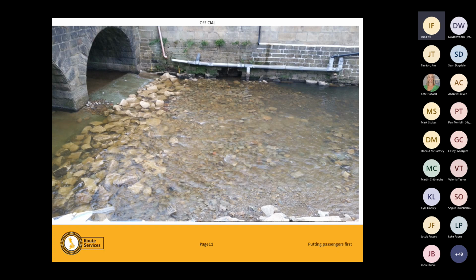So you've got fast moving water coming along through the structure, you've got slow moving water in the channel, and they crash into each other. And again, you get a lot of turbulence, a lot of energy. And what happens is that water starts to rotate and dive, and it starts to eat underneath the concrete. So if you've got no transition material here, you still get the fast water, the slow water, but it can't eat away at the rock. So you have to have that. It's poor design when you don't have that transition material at the end of a hard invert.